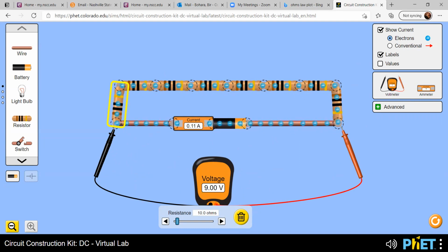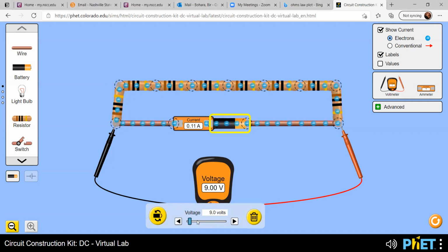Now your job is to measure voltage and current. That's all. So first set the selected voltage 20. From here, voltage, if you click it here, you can set this one to 20. Right? So if you set 20, your current is 0.25. Right? So your next data, you can write it down here.